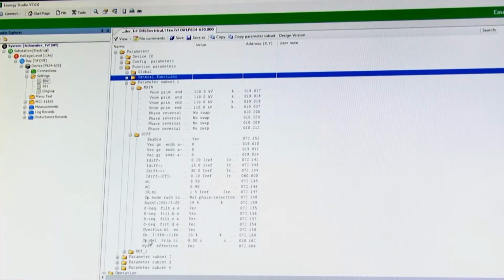In addition to that, we have several settings. For the percentage bias relay, we have the overflow setting and the percentage of fifth harmonic. We have the second harmonic inverse setting of 29% here, and the fifth harmonic setting is 20% here for this case. So, this shows us the overall setting carried out for a particular case, which we would like to verify and demonstrate in this experiment.